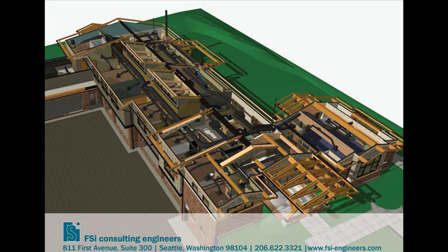Yeah. The thing that I think really speeds up using Revit versus CAD is that we use 2D CAD; we don't do a lot of 3D CAD. If we were as-building in CAD, we would not only have to show the diameter and size of the ducts and where they start and finish, but we'd also have to include the height of the duct. In Revit, you can just pick a 16-inch duct that starts approximately here in plan, at 10 feet above the floor I'm standing on, and you draw the duct. Then you say it drops down 5 feet, change your orientation, click down, and it makes all the elbows and transitions for you.